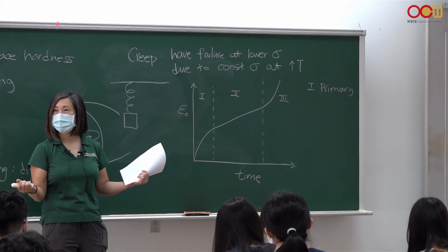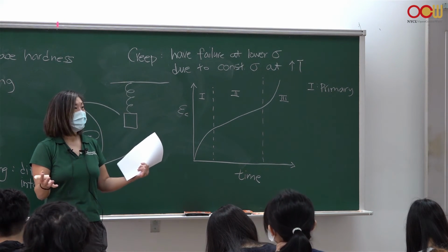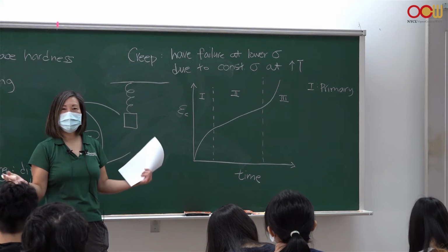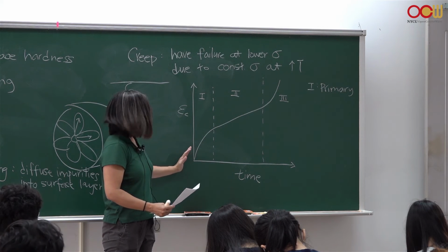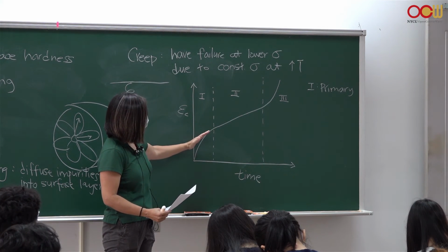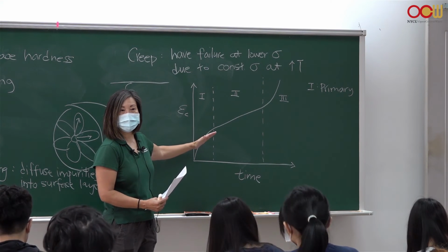You apply stress to any material, you're going to get elastic deformation, right? So you can't prevent that at any temperature. There's going to be some bond stretching, so there will be some strain. But the strain you'll see is starting to decrease with time. The growth of that strain is decreasing with time.